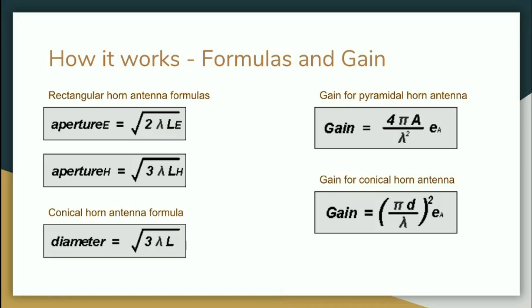gain and directivity. The reason for this is that the aperture of the horn remains constant in terms of physical dimensions, but increases in terms of wavelength. Antennas tend to have higher gain levels as they become larger, so it can be intuitively seen that the gain and directivity of the horn antenna will increase with frequency. Gain and directivity are shown in the following formulas.